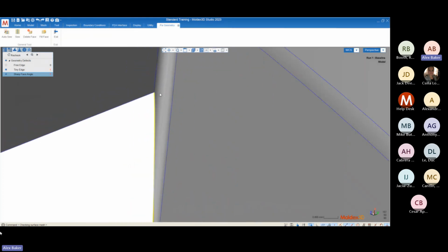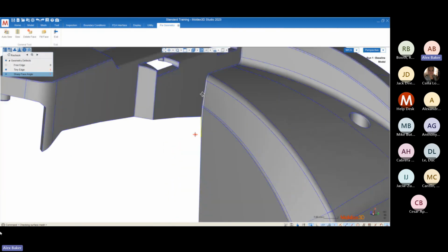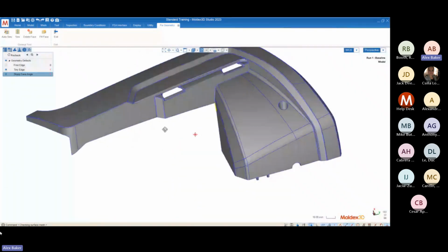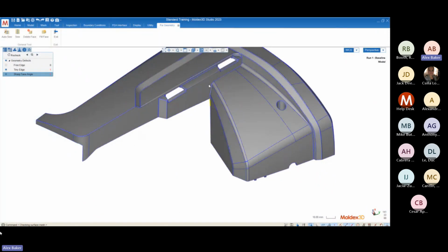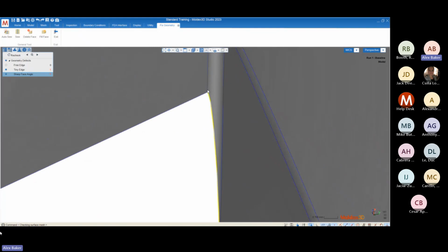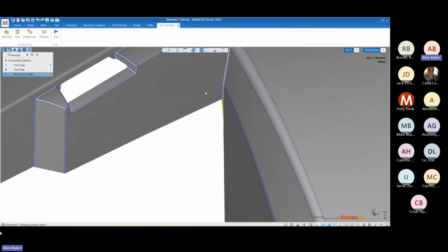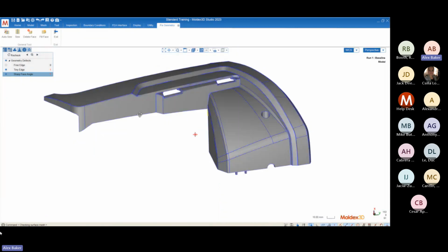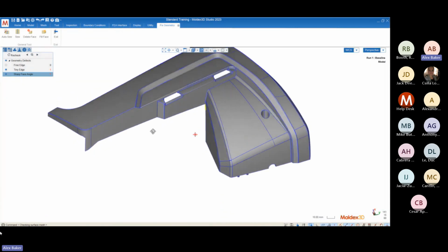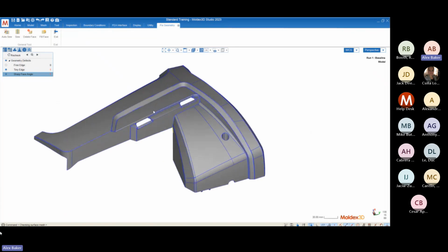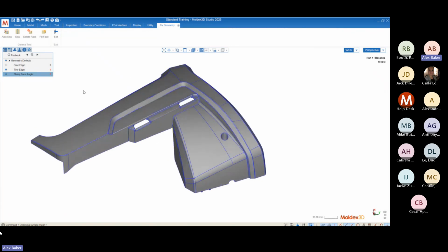In some cases, you'll get a bad orthogonality error or some other solid meshing error where we cannot fill in solid mesh in that small volume. In those cases, we might recommend to either remove the feature or try to open up that angle as much as possible once you get to the surface mesh. Again, these aren't make or break problems because they're not guaranteed to cause any sort of problem in the meshing, but we do recommend you to at least be aware of their presence.